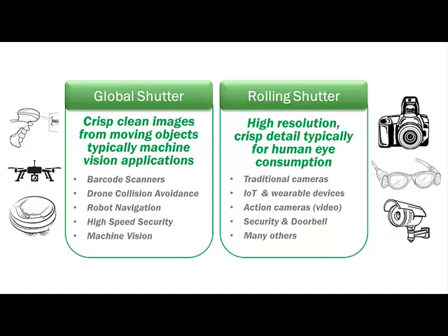The downside of global shutter technology is that it's hard to shrink to smaller pixels, which ultimately ends up limiting resolution to a given size. The technology also costs more, and it's more difficult to use absolute cutting-edge pixel technologies because of the need for storage node and more complicated readout methods. Both types of products definitely have their place. When you need to consider a global shutter image sensor for your application, it's important to find one that will adequately fit your needs.